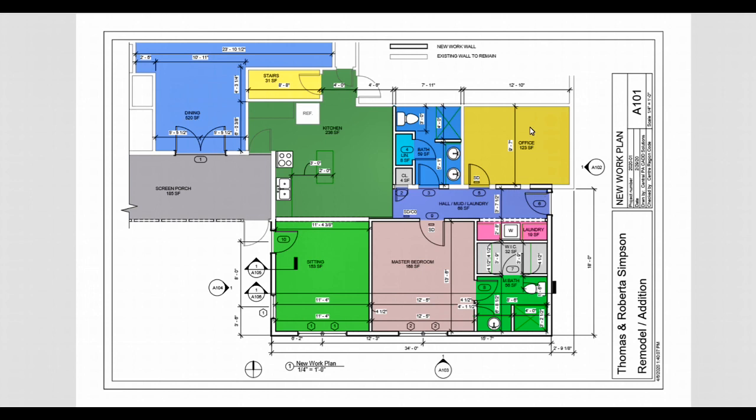Typically, I'm not going to include any drywall on the interior dimensions. So whenever I look at this dimension right here, this 9'7", that's going to go from the face of the stud to the face of the stud. And the reason for doing that is whenever I'm installing these walls, I'm not going to have any drywall in place, and I don't want the contractors to sit there and have to do that math every time where they're subtracting out a 1/2 inch for each drywall, or even more confusing if you're using like a 5/8 inch thick drywall.